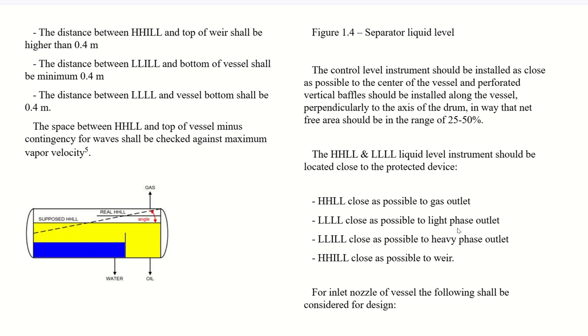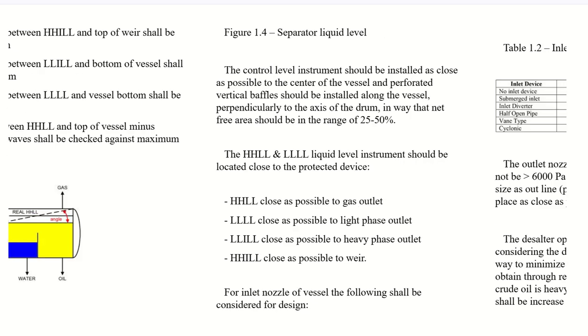So you can see this is a kind of three-phase separator. We can see the water is there in blue, and there's a baffle, and then oil overflows the baffle and comes out. So this gives typical criteria about interface levels, interface level plus oil and water level actually. So this comes under three-phase separator criteria. We will discuss more on this when I produce a separate video on three-phase vessels, and then we'll go into more elaboration on that.